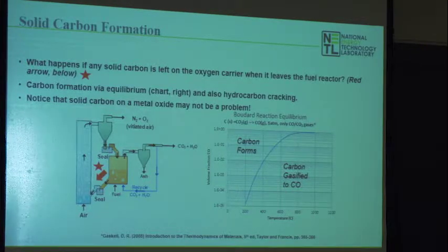Air reactors at high temperature, air, carbon, mix, CO2, right? The very thing you were trying to avoid and keep isolated. So you can't afford to have carbon forming on that surface and then getting carried over into the air reactor. You can't have any leftover solid carbon make it through. So in fact, in our lab, and others as well, we're looking at devices to make sure any leftover residual solid carbon gets kicked back into the fuel reactor.